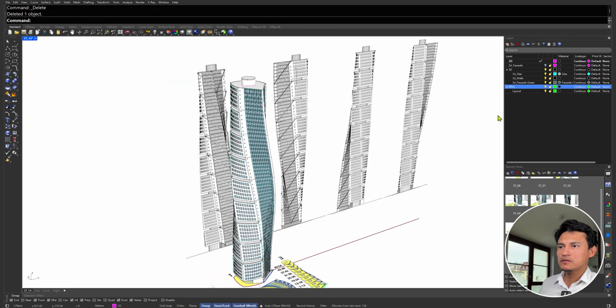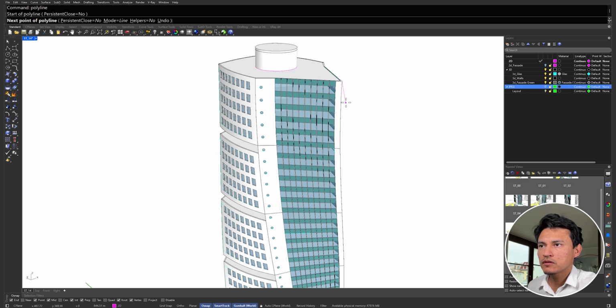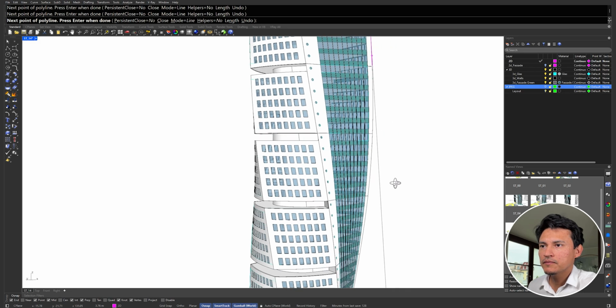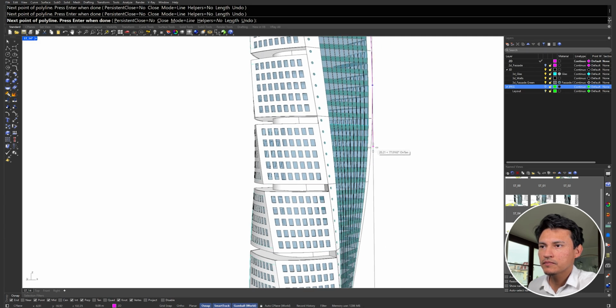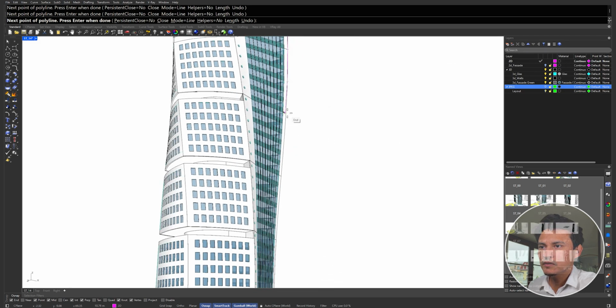Looking good there, but we're still not finished. We're missing the outer structure that looks like a spine. For that, I'm going to draw this control point spline, and I'm going to use the outline of the facade of the main building.